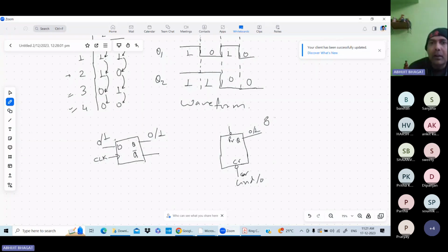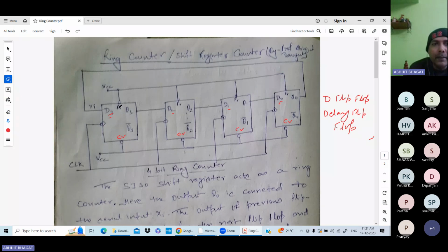Next, after that, for the normal operation, that is, when you use this flip flop for operation, all this preset and clear is connected to VCC. When it is used in normal operation, it is connected to VCC. Clear? So same here, for the normal operation, when you want to use it, this preset and clear is connected to VCC. Okay, for the normal operation.